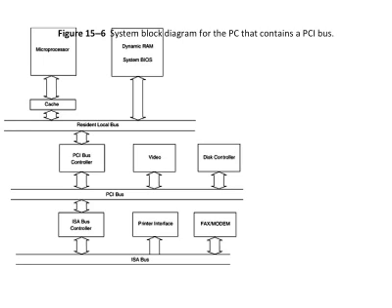This is a simplified picture showing the architecture of these different buses within a computer system. The microprocessor may or may not have an off-chip cache. Then the microprocessor and the cache are connected to the memory subsystem on the so-called local bus, or front-side bus, using Intel's term. This bus is high speed, sometimes running at over a gigahertz, and it is connected to the PCI bus through a bridge or bus controller. On this PCI bus, you can have all these different kinds of devices. In this example, we have a video graphics card, we have this controller, and we can even connect this bus with other buses through another controller, sometimes called a bridge chip.